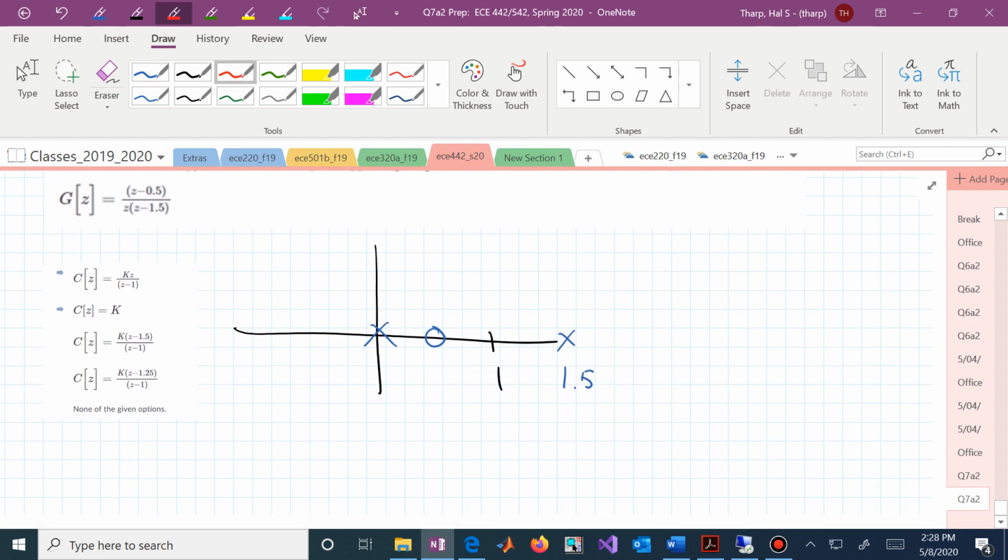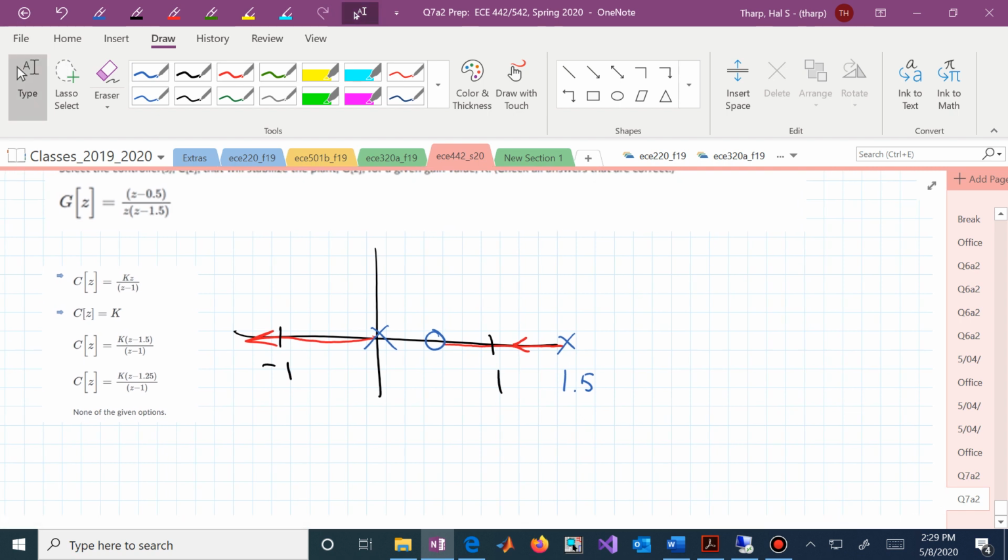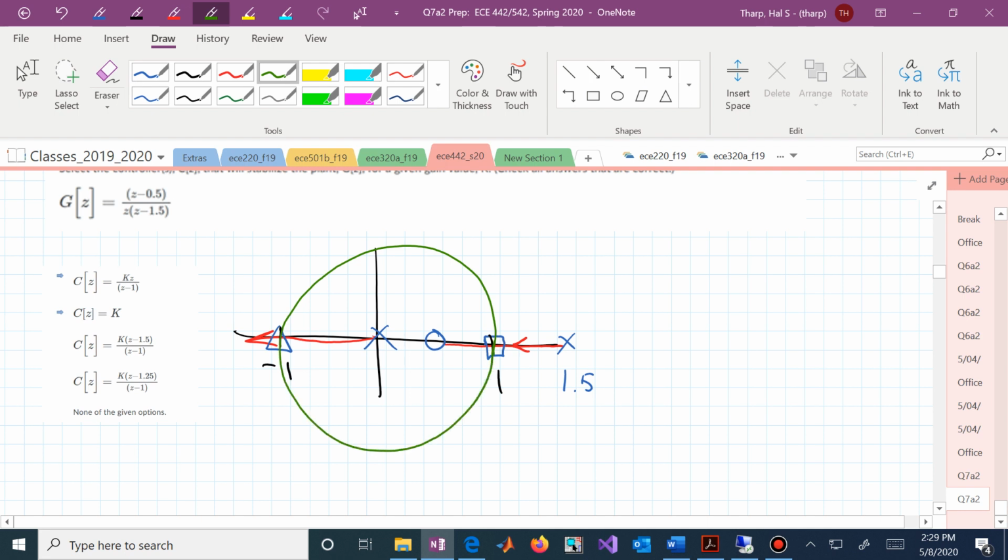Well, if we look at this just with a constant gain controller, then we need to investigate what's happening at this particular value of gain versus this gain. If the gain to get us inside the unit circle on the right is smaller than the gain to get us outside the unit circle, then this controller would be okay.